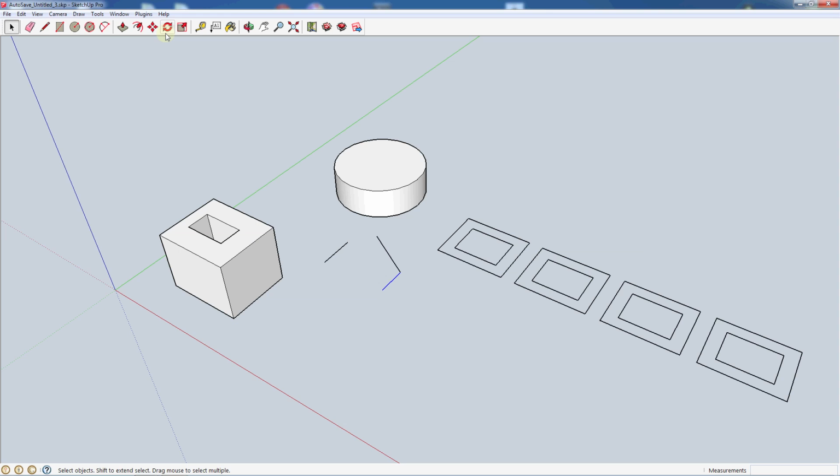All right, the next tool we want to talk about is our rotate tool. And this can interact with individual parts of an object or a whole object, depending on how they're grouped. And it will do it on various planes. So you see, as we grab the tool, by default it's going into the blue plane. That would be the top-down plane. Like if we were on the top of a surface, that's the plane we would see there. You also have our red face or plane, and then our green face or plane. So you want to keep that in mind as you're moving them, and if you're not on an exact one, it's going to show up as black because it's not snapping exactly to one of those planes.